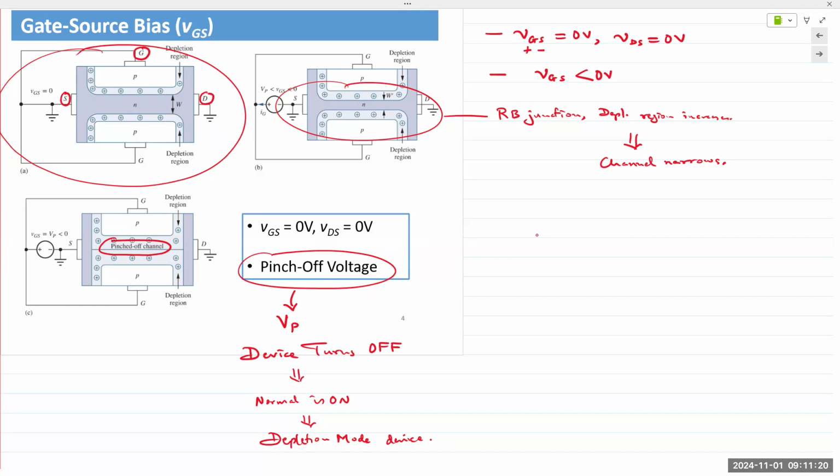And because it's an N-type material, there is an abundance of negatively charged electrons that are available to conduct charge. If you apply a voltage between the drain and the source, meaning across the channel, you'd expect electrons to move and current to flow as a result, right? Then we have the gate.